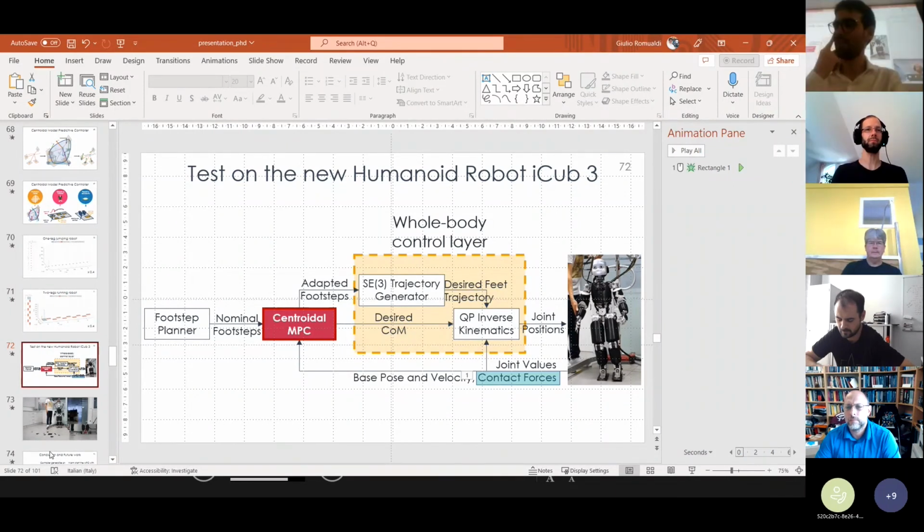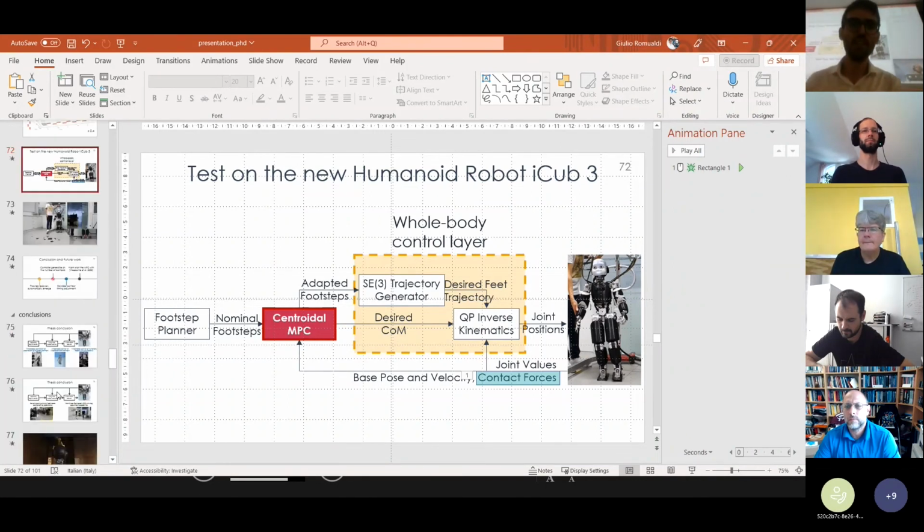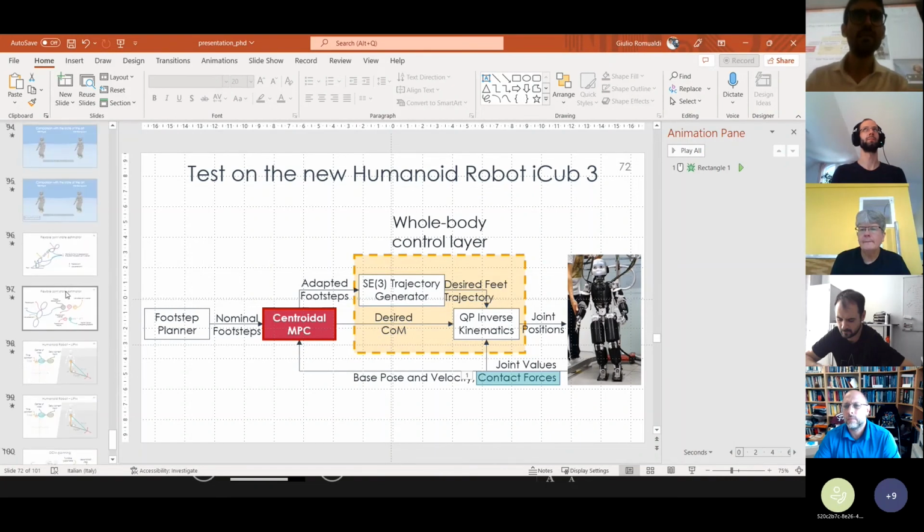I completely understood the question. Regarding this centroidal MPC, we try to minimize the angular momentum. One of the main ideas is to remove this minimization and use this human-like trajectory motion generator to compute a desired reference, even if it's not feasible, but a reference that makes sense for the angular momentum, using the desired quantities coming from this network along with the centroidal momentum matrix, because then we can compute the angular momentum. And this can also be considered here. Let me go back to this slide.